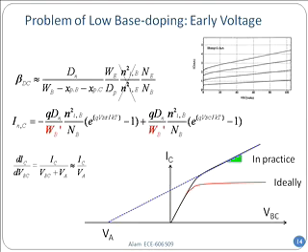So compared to that, I can always neglect VBC. VBC is on the order of maybe a volt or so. So I can drop that. And therefore, in a reasonably good transistor, I can say IC over VA is the measure of the slope of this bad effect of low doping. And this is named after Jim Early, and it is called the Early voltage. The V sub A is called the Early voltage. So if somebody says to you, I have a large Early voltage, that means he has just designed a transistor which doesn't have this base doping problem. That's what he's trying to tell you.